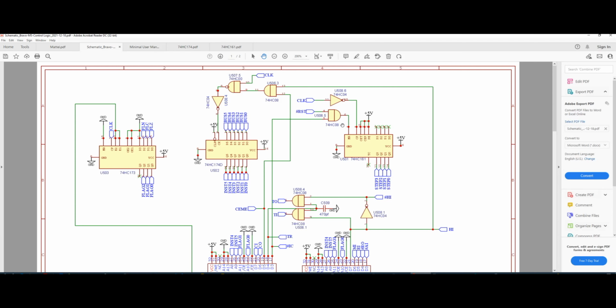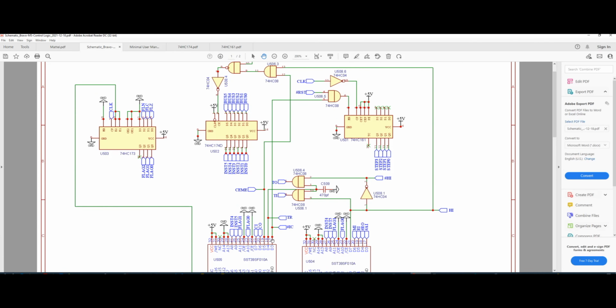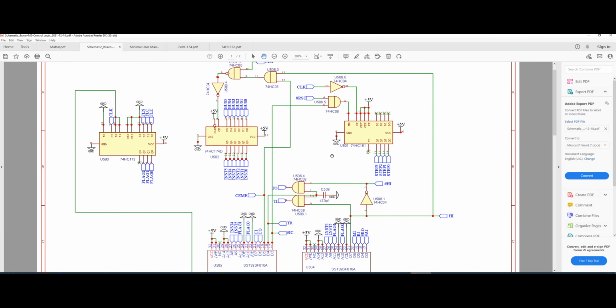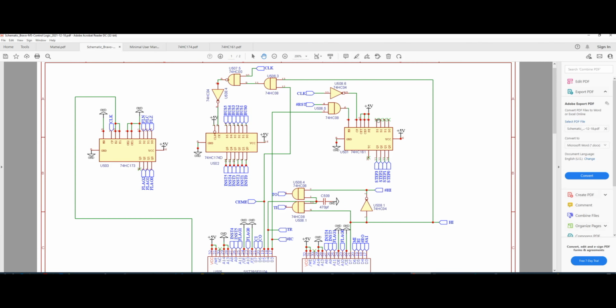So that's a great mechanism here, because we will be saving a lot of unnecessary clock cycles, meaning that if a micro instruction is only 5 steps, we are really running this counter for 5 steps, and after that we're just going to stop the counting by resetting the circuit. So that's a cool thing, and of course in order to do that we need one extra signal, which is called IC, but again, that is very useful since it could save a lot of clock cycles during the execution. Now, I hope that the input side of those chips is clear.